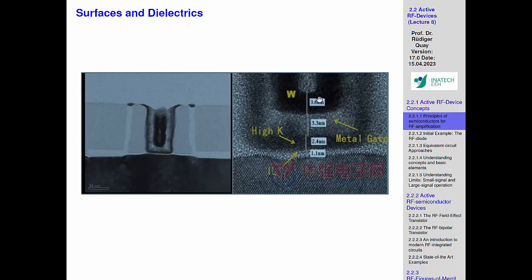That's one thing. But even if you keep that in vacuum, if you just interrupt the crystal, we have a lot of charge potentially there. And what we don't know is whether these charges are really free floating, or whether, because of the interruption of the crystal, we create some kind of trap. Trapping is a very critical story, because it's like a situation where you replace something in the crystal by something else, which is doping, for example. And there can be all kinds of traps, and the problem is this is very likely to occur.